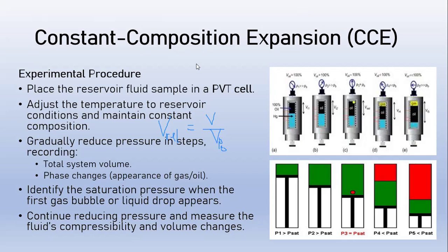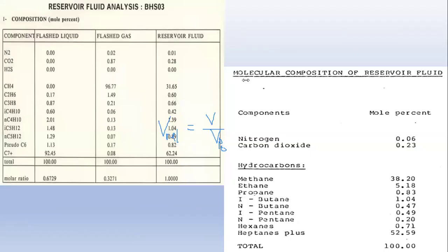Sir, I have a question, sir. Okay, Mr. Samuel. From the compositional analysis results you showed us, are we going to add the gas and oil together to get the reservoir fluid or what? Because I don't understand how we get that one. It will come in just as it is like this. You are not supposed to add anything. The only thing you will do is QC these values to make sure there are no errors.